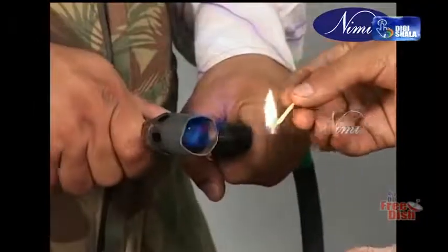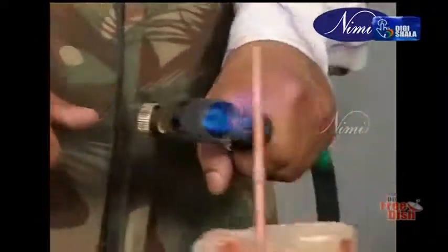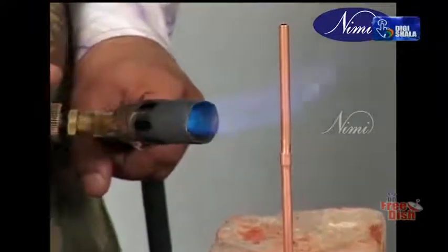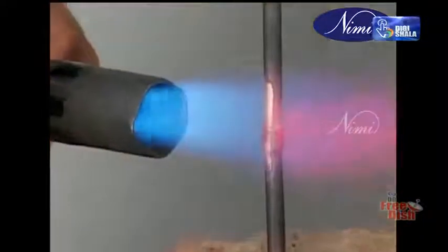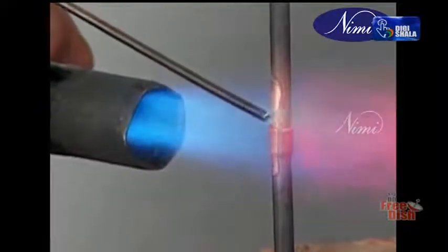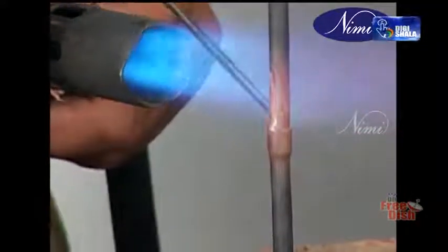With the help of a blowtorch, propane, acetylene, blow lamp kerosene, flux and brazing rod, we can make a good leak-proof joint as it is showing. We must be careful at the time of brazing. Proper flux should be used. Touch the brazing rod on the joint after it gets red hot.